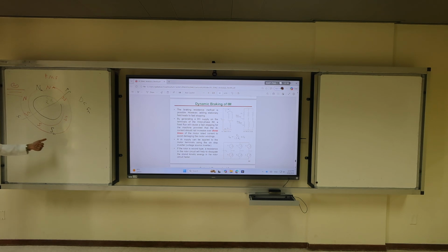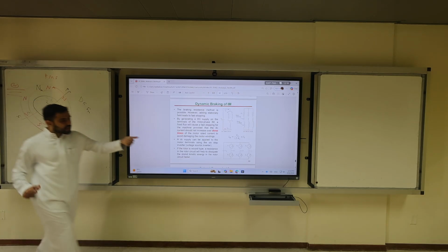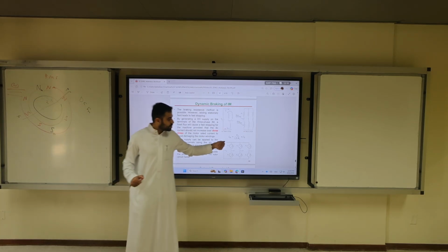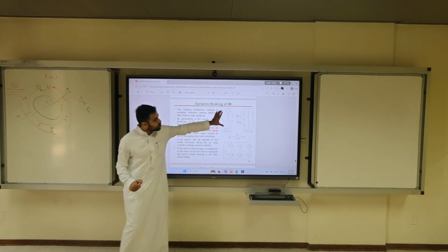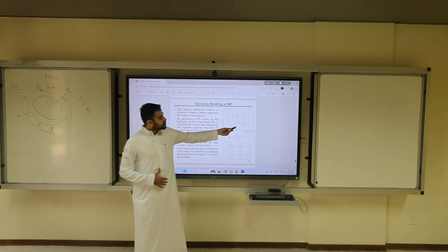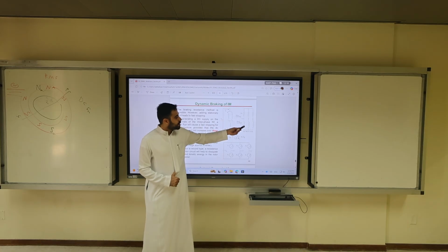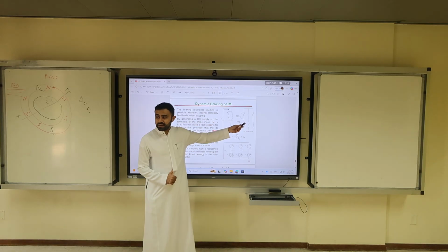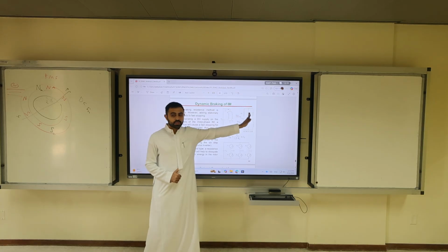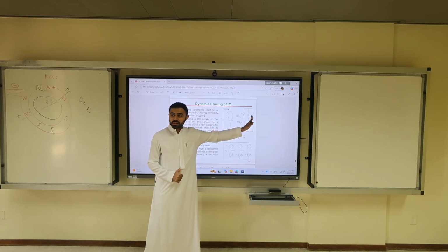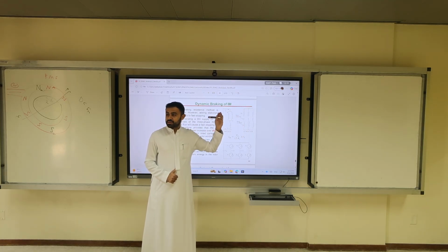It's a very easy concept, but you need a VSI, voltage source inverter, to do it using the switching. So this is how we connect it. In the rotor circuit we have RB and rotor windings. The rotor would have a rotating magnetic field that will lock with the magnetic field generated by the DC. This is on the stator, and this is on the rotor. This is a very important braking concept, okay?